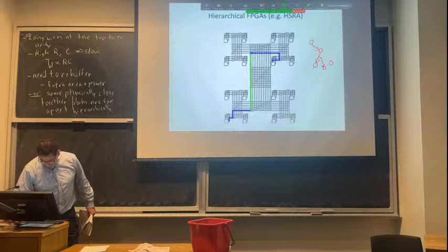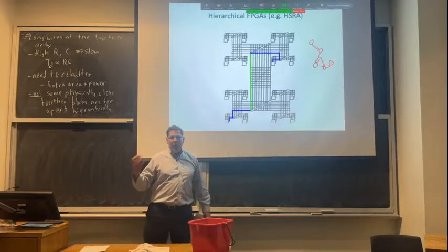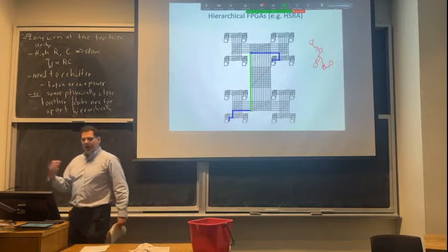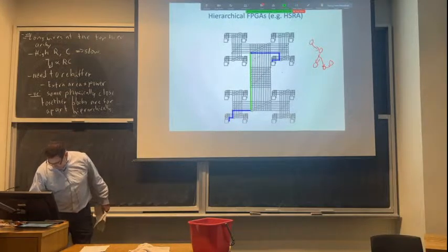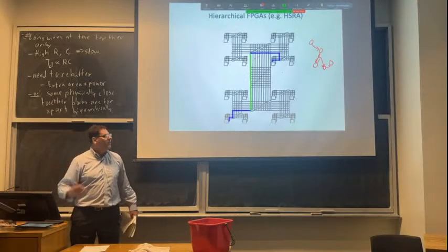Basically your design to a CAD tool looks like a whole bunch of nodes and edges, where the nodes are blocks and the edges are hyperedges. A hyperedge just means an edge that has one start point and multiple destinations. That's a hyperedge, also called a net.